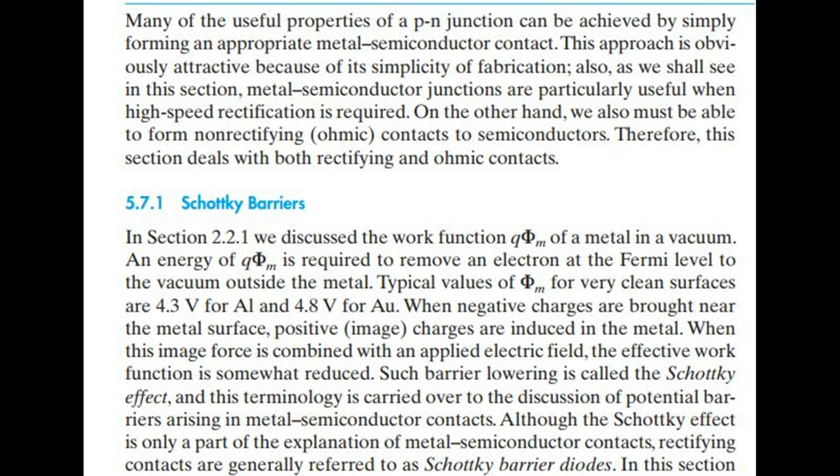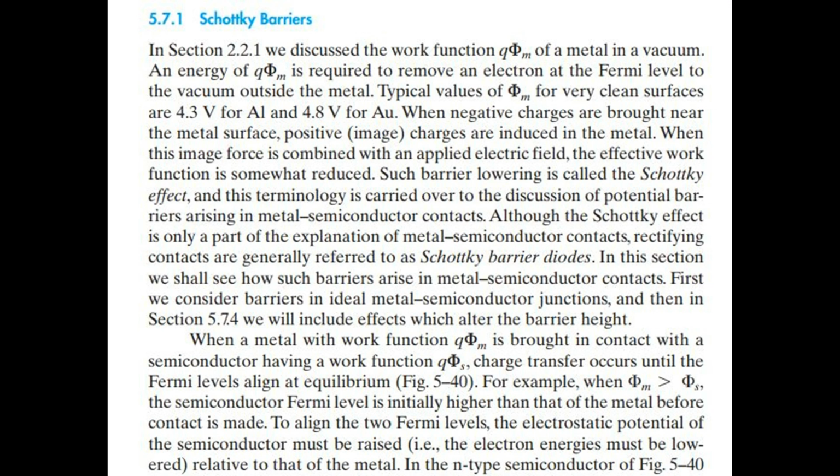Such barrier lowering is called the Schottky effect, and this terminology is carried over to the discussion of potential barriers arising in metal-semiconductor contacts. Although the Schottky effect is only a part of the explanation of metal-semiconductor contacts, rectifying contacts are generally referred to as Schottky barrier diodes. In this section we shall see how such barriers arise in metal-semiconductor contacts.